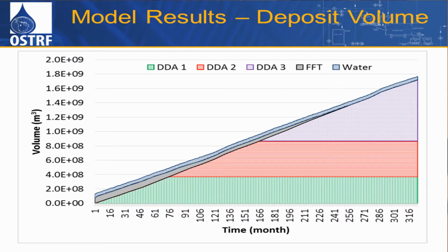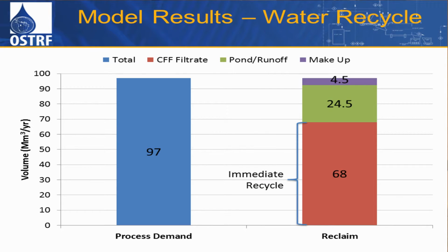In this successful model, we had 1.7 billion cubic meters of Crosswell filtration tailings deposited back into the pit. We were able to consume about 100 million cubic meters of MFT through the spiking process, so all the MFT that was on this model mine plan site. And we maintained our stockpile of process water at about 40 million cubic meters.